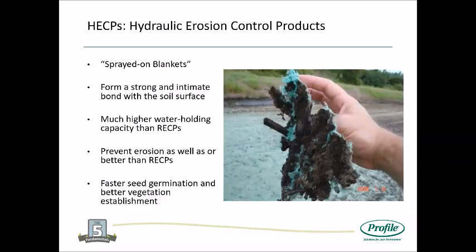Here's a quick view of Flexterra, our highest performer applied to a soil. It adheres to the soil very, very quickly. It holds a lot of moisture near the seed, so vegetation will thrive and do well and germinate very quickly. Again, this is more of a sprayed on blanket, so we want 100% coverage on our soil. If you see soil, you don't have protected soil. So making sure you get 100% coverage for these high-end erosion control products is absolutely vital to your success.